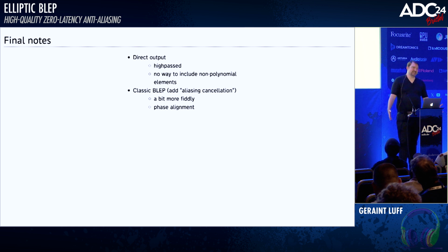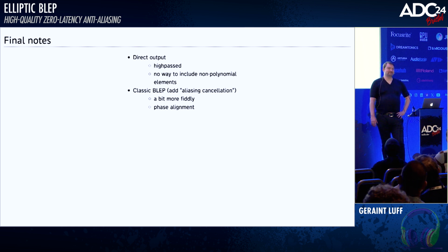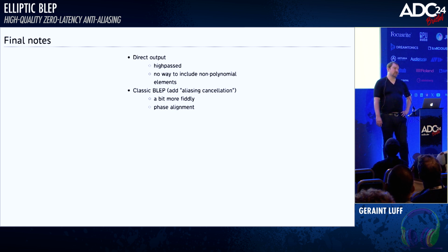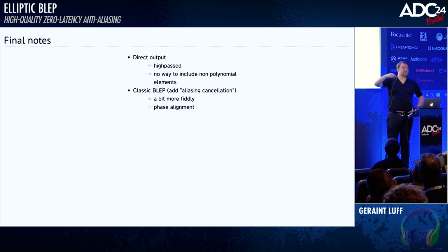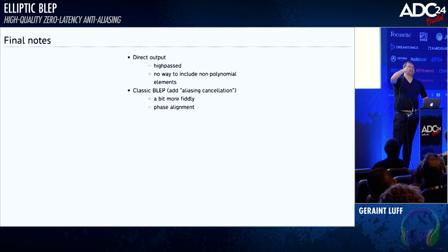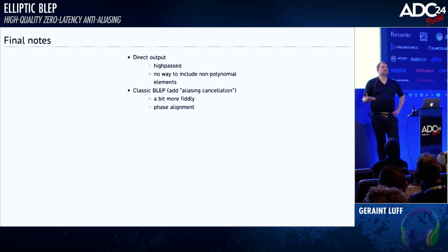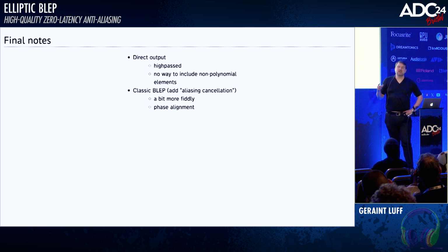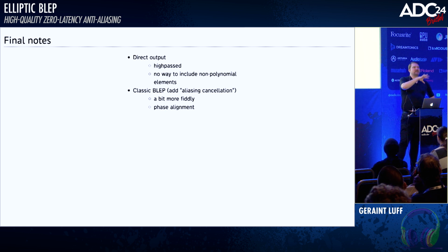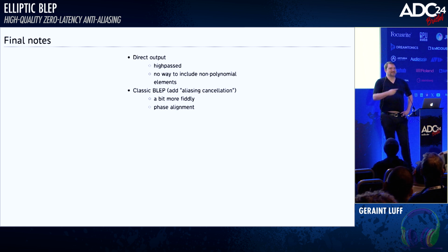And then, I didn't really mention this at the time, but it is important. The elliptic low pass has a very nonlinear phase response. So in the case of a hard synced sine wave, there's going to be some interaction between the regular impulses or steps, the discontinuities from the hard sync, and the actual phase of the sine wave. And I don't have the graphs anymore because I changed dev machines and nothing worked anymore. But the exact phase relationship changes if there is a phase shift applied to the discontinuity as part of low passing it and not to the actual sine wave bit.